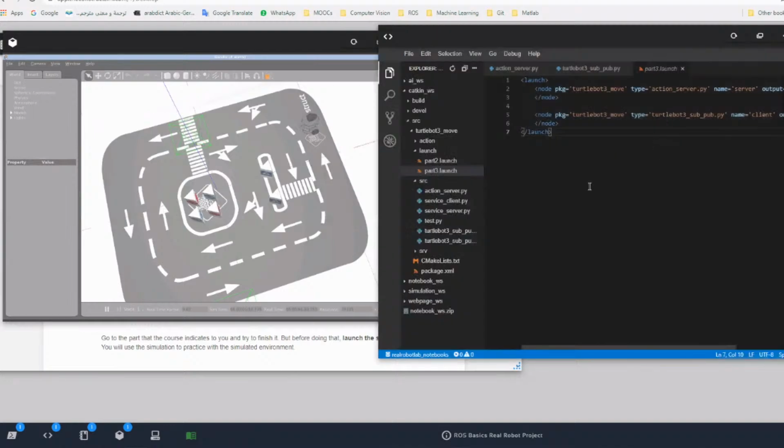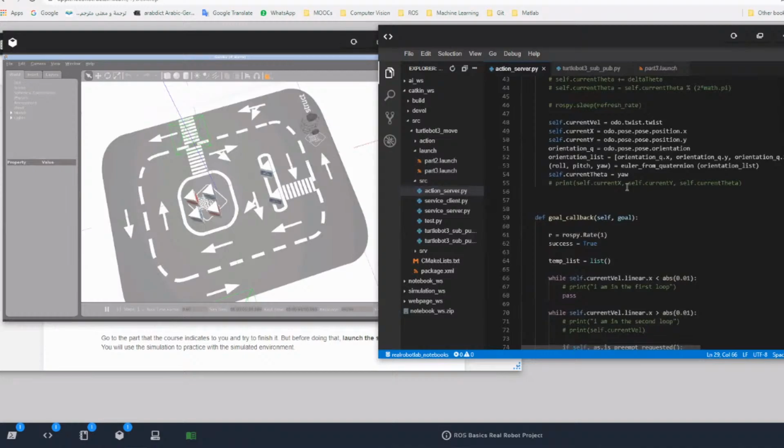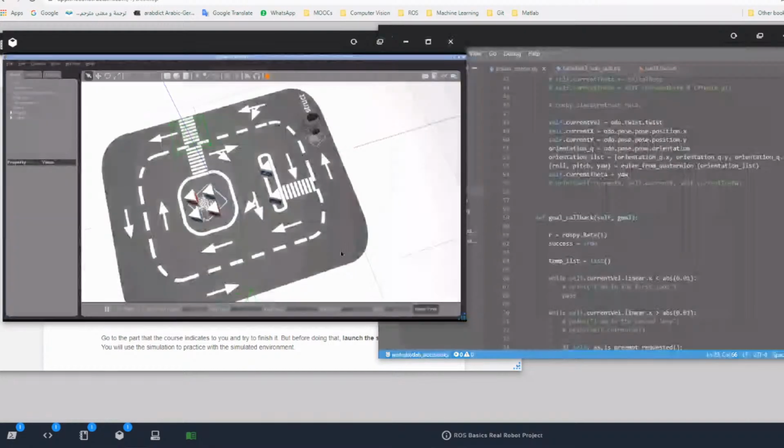Yeah, actually, it's correct. That's interesting. The odometry readings are not perfect, as much as I understood. So it's not like the readings we got from the Gazebo position. It has some kind of error. Definitely, and the more it runs, the more the odometry will drift in the real robot.